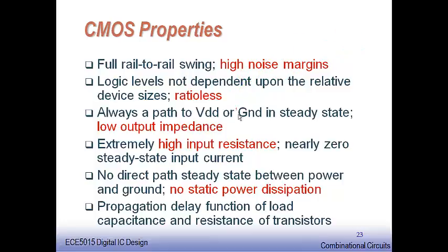Now there always exists a steady state path between the output node and VDD or the output node and ground. Therefore, at no point of time do you have any node in a floating condition. This is the biggest advantage in these circuits. Because there is no floating output node, the circuits are not very vulnerable to other effects such as crosstalk, leakages and interference.